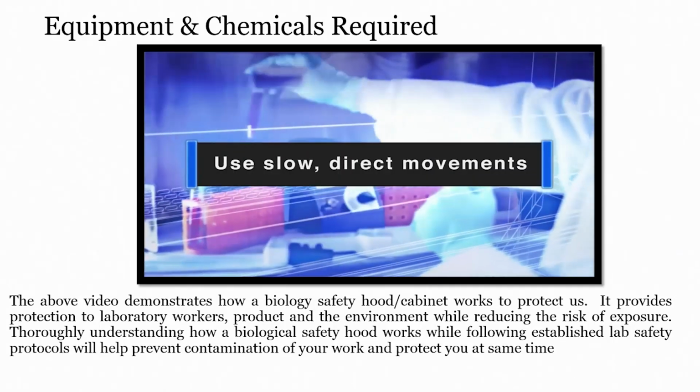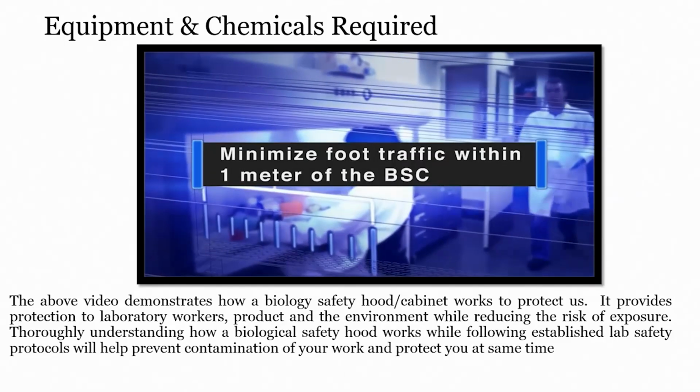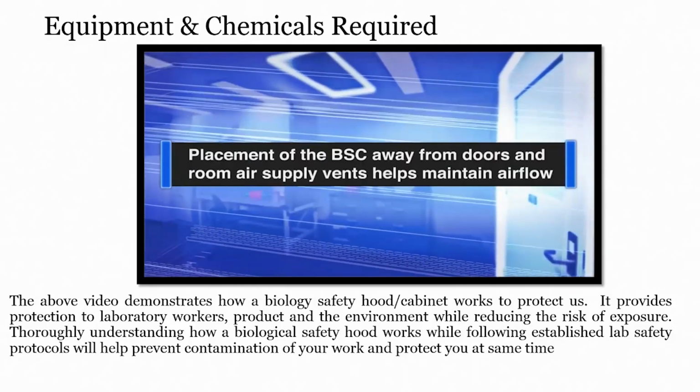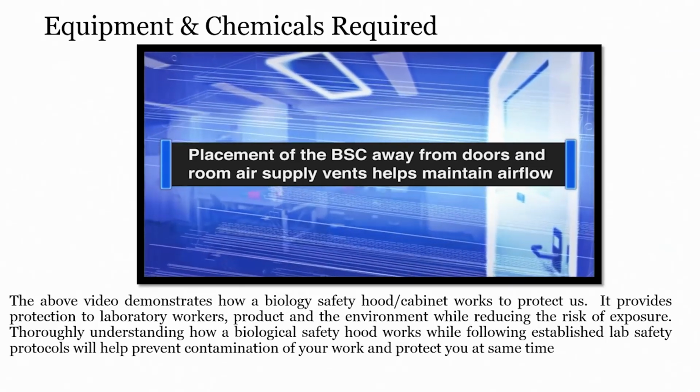Use slow, direct movements. Minimize foot traffic within 1 meter of the BSC. Placement of the BSC away from doors and room air supply vents helps maintain airflow.